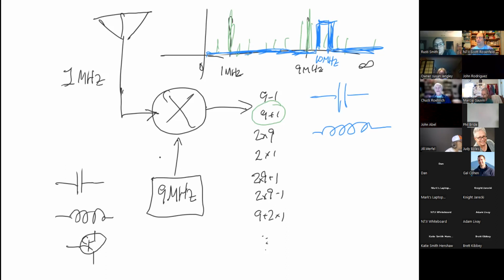It's not going to do anything. What's the purpose of sending your tweeter sounds to your subwoofer that's sitting on the back window of your car? The answer is there's no point. So by using capacitors and inductors, we can make a frequency sensitive filter that allows us to just send frequencies that we care about to places we care about.